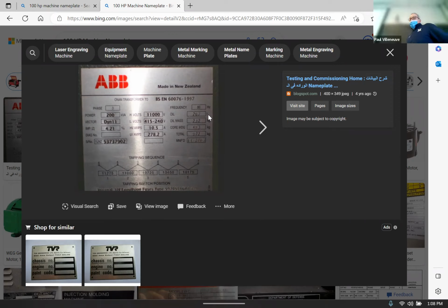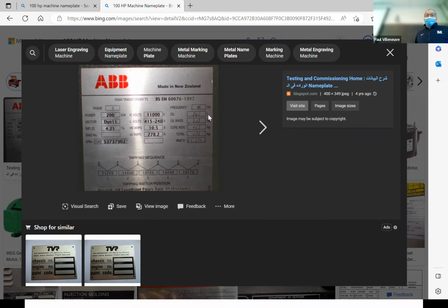Yeah, once water starts to get in around the windings, you can usually get yourself some problems. But he's doing submersible stuff that's actually underwater. So I would say that's not the norm. Oil filled is common though. Oil filled motors or submersible stuff. Yeah, all of our submersible stuff is always oil filled, generally speaking.